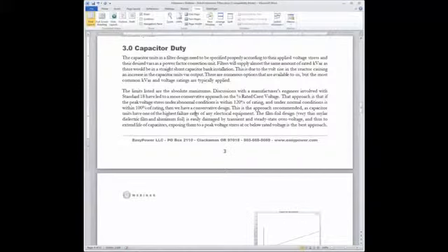What will happen is the peaks of each one of the waveforms. We have the fundamental being our first one, and let's say we're absorbing predominantly fifth harmonic. The peak of that fifth harmonic voltage has the ability of being impressed completely in line with the fundamental.